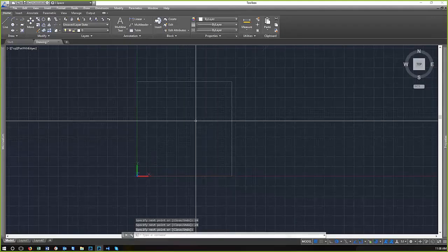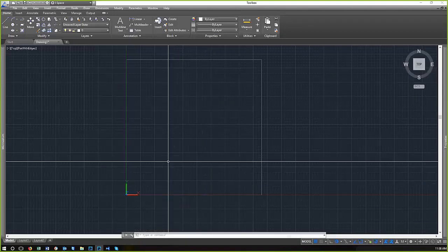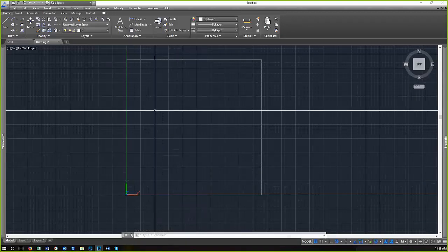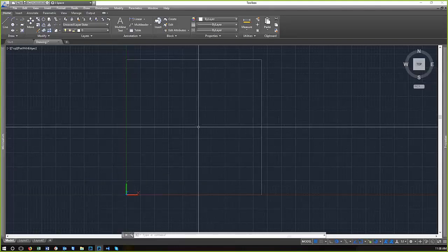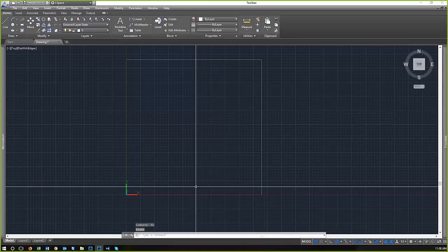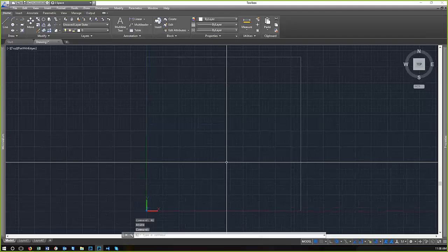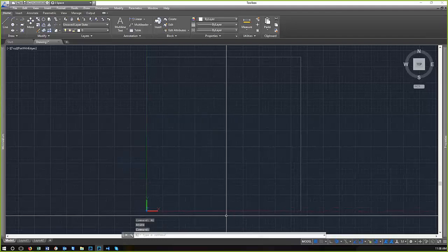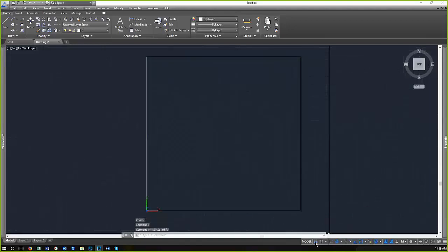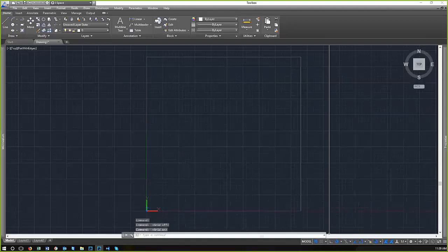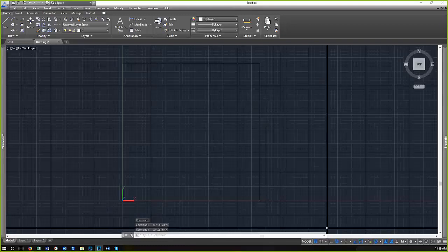And then I'm going to regenerate. It's a helpful command. RE refreshes everything that you can see, and it will redraw the objects on your monitor. So I'm going to hit RE just to refresh. Okay. It didn't have the effect I was looking for. I was hoping that this grid would get a little bit smaller. I tend to not work with that grid on. You can turn it off. But to help you see what we're working with and that things are actually changing, I'm going to leave it on just for now.